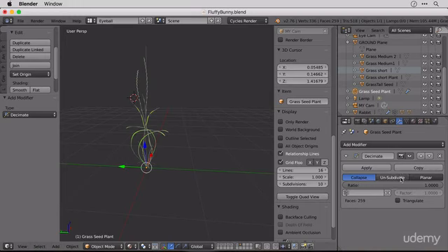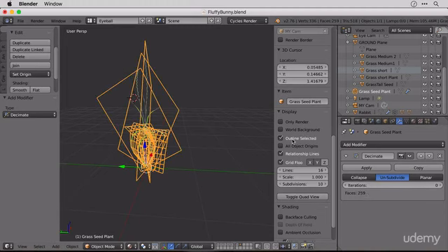Now I'm going to use unsubdivide for this one, and we can see I've got 259 faces, and if I turn on the outline again, we can see that most of them are on these small blades of grass crisscrossing one another. So I'm just going to increase these iterations, and it looks like the lowest number of faces I can get is around 5 iterations, and 23 faces. Interestingly, you get less at number 4. Okay, so let's see what it looks like at number 4.